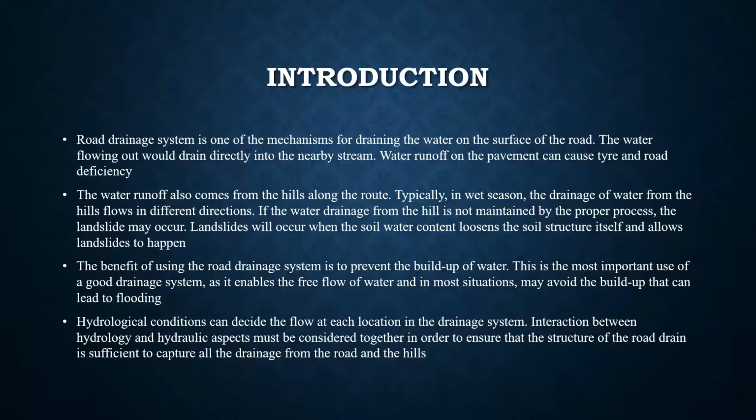For this project, each group is required to apply the knowledge of hydraulics to design the size for the chosen drain system. So we need to determine and label the type of drain suitable along the proposed road for CH 0.0 meter to CH 100.0 meter. Other than that, we need to analyze and sketch the direction of flow within the drain along the proposed 225-meter long road. Consider the rational method for 20-year ARI event and Kampung Sungai Yap rainfall station.